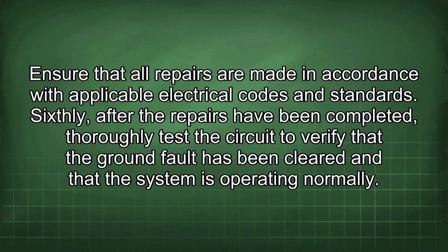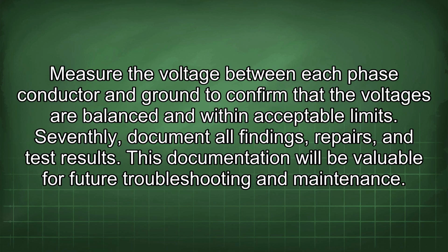Ensure that all repairs are made in accordance with applicable electrical codes and standards. Sixthly, after the repairs have been completed, thoroughly test the circuit to verify that the ground fault has been cleared and that the system is operating normally. Measure the voltage between each phase conductor and ground to confirm that the voltages are balanced and within acceptable limits.